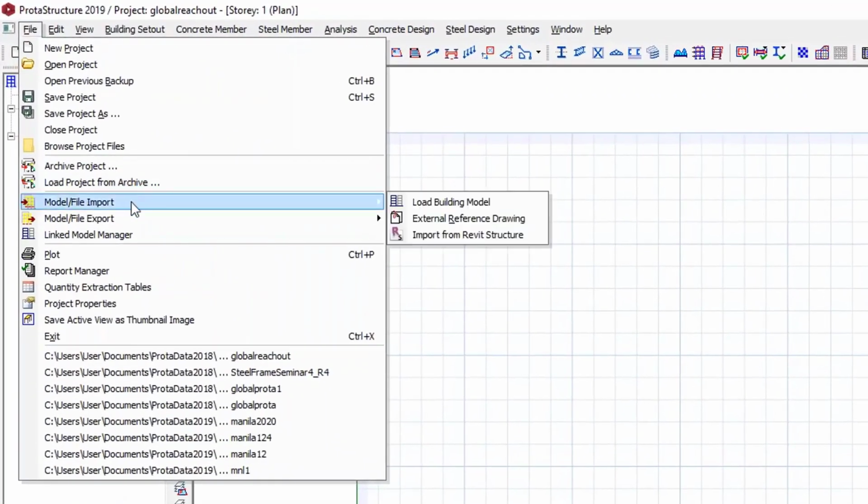Now, when you are in the modeling environment, you can start in different ways depending on the information that you have. If you have an architectural drawing, you can import this. Maybe it's a layout plan with grid lines and so on. You can extract information from this, so you can pull off grid lines and columns to help you set up the model. If you have information from BIM, maybe basic Revit information, this can be imported as well.